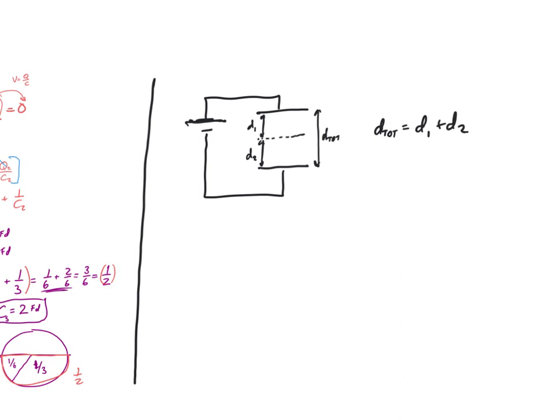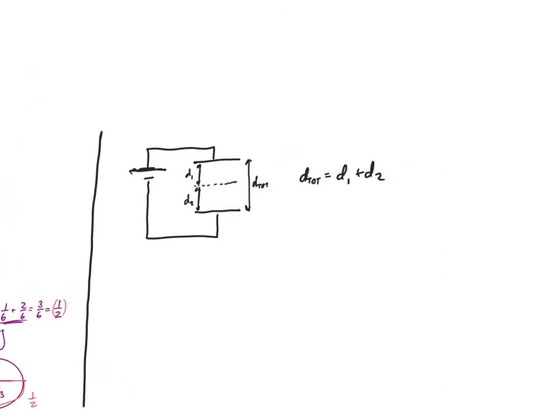All right. Now for this one, I can try to get it to look like the capacitor design equation, C equals A permittivity over D. Kind of. Because the D is already in a numerator. So instead, I'm not going to make it look like the capacitor design equation. Instead, I'm going to make it look like the inverse of the capacitor design equation, which would be D over area permittivity.